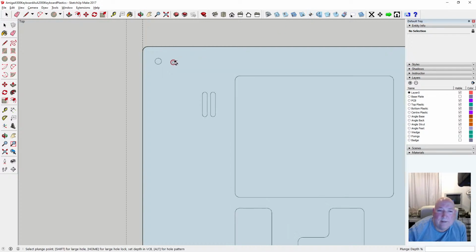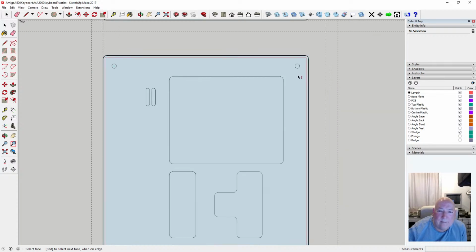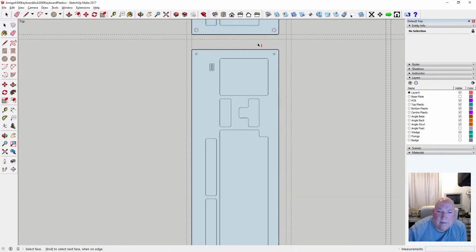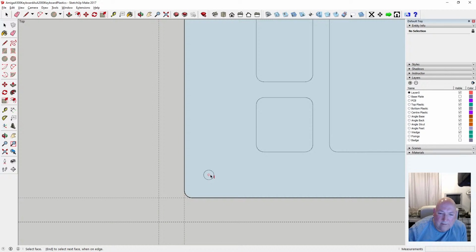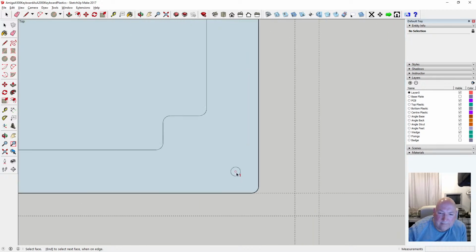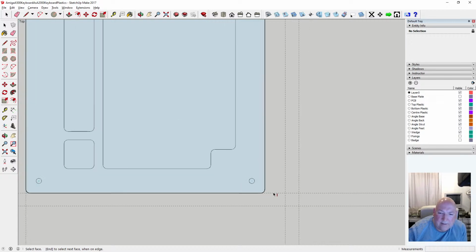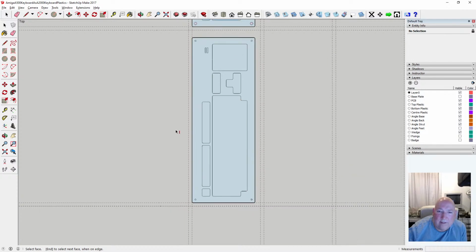Plunge it. Maybe I don't want to plunge. No, because what we want is an inside cut, because that'll only give us the wrong size fixing hole. Let's do an inside cut then. There's 1, 2. You only plunge it if you've got the same size bit as you want to drill a hole. Alright, that's okay. Right, so we've done them. What else is there to do?